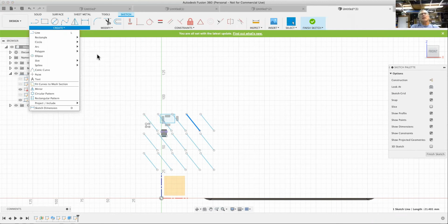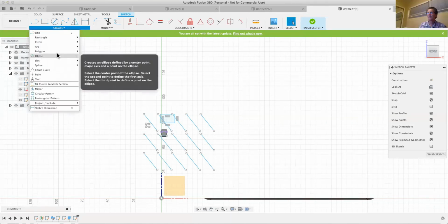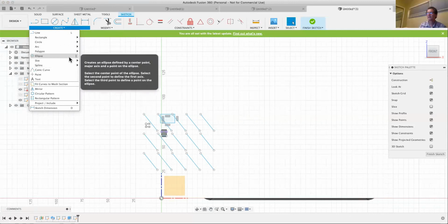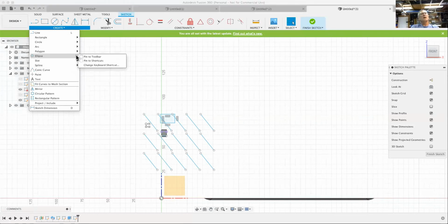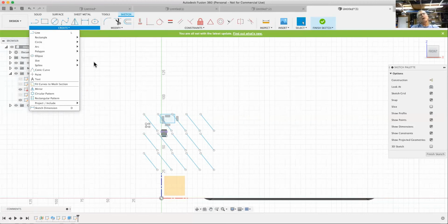Hey Tim, just out of curiosity, we are in sketch mode, and the icons we see on the toolbar range from line to square, etc., to dimension. Those are totally customizable by what you saw in the ellipses. So you could unselect to have the line show up in the toolbar in the create menu, right? So for example, if I want polygon up there. Well, actually, that doesn't have any ellipses, come to think of it. Well, maybe it does in the submenu, though. There, ellipse has an ellipsis. I can pin this to toolbar and there it is. Okay, great. Thank you.